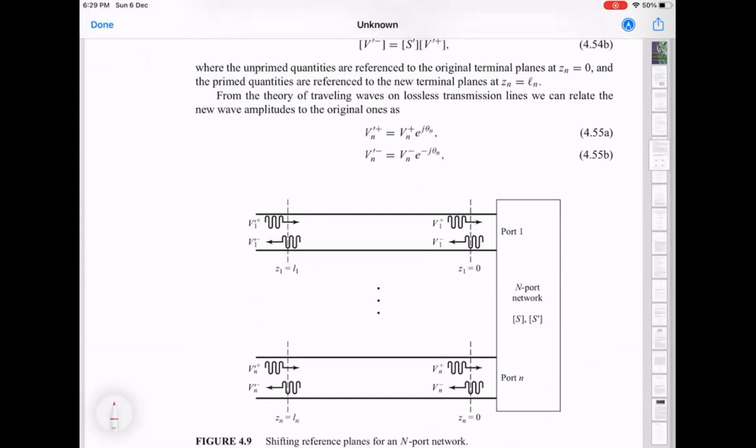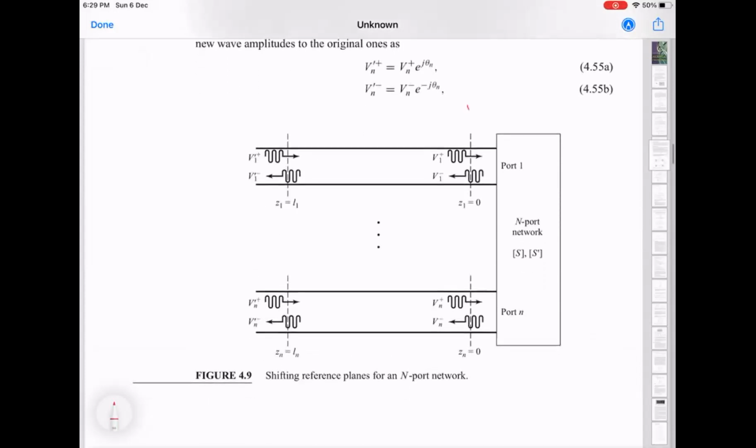This is practical in the following way. You see this object here is the device which allows you to measure the scattering parameters, okay? Which means that anything which is connected at this reference plane and this reference plane, this instrument will give you the correct scattering parameter for that particular device. In this case, let's say it's 2-port or N-port, it doesn't matter.